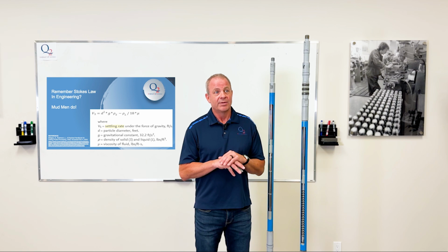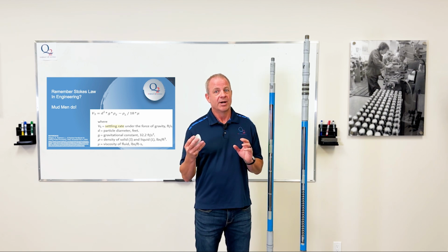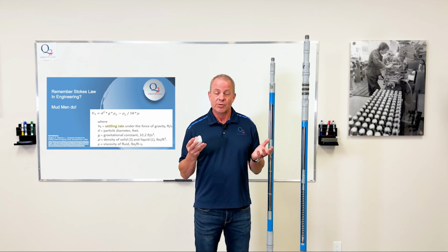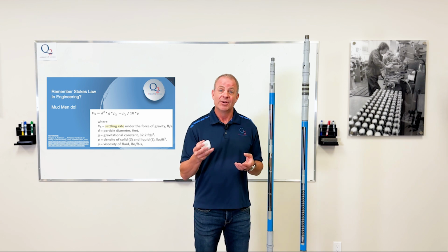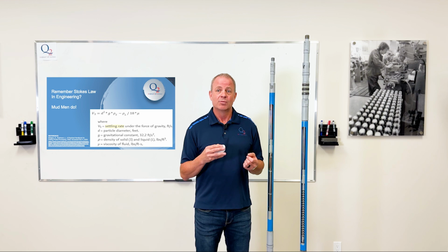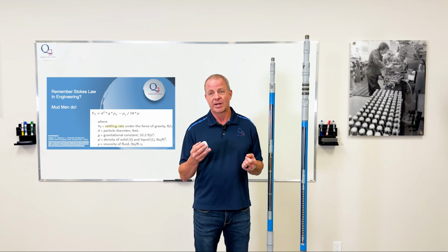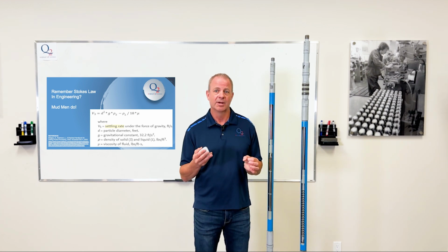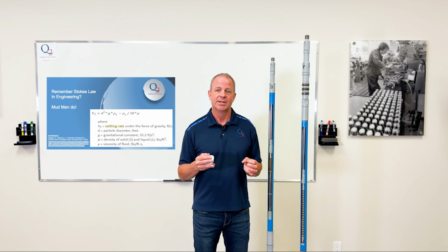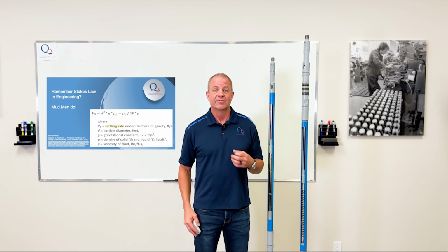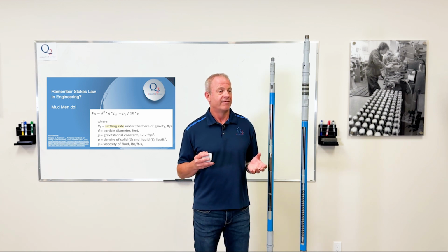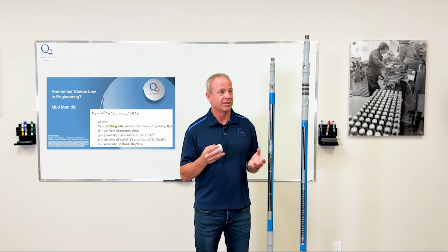Now everybody, I'd like to get you back to the old days of these formulas you learned in engineering. So, Stokes' law. Do you remember that theory? I know that engineers do, and I know that the drilling fluid men, mud men, do. This is the formula for settling rate under the force of gravity for solids. The particle size is another part of the formula, the gravitational constant is in there, and the density of the solid. And then, of course, the viscosity, the carrying capacity. But with Stokes' law, you have these variables with respect to settling.